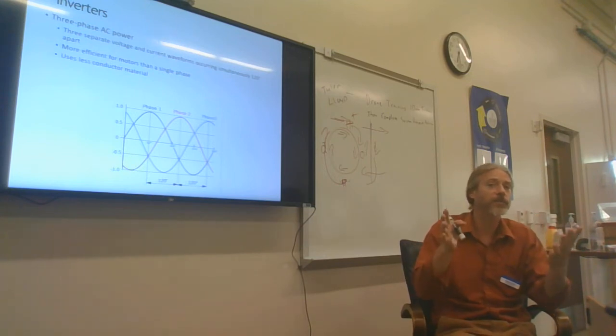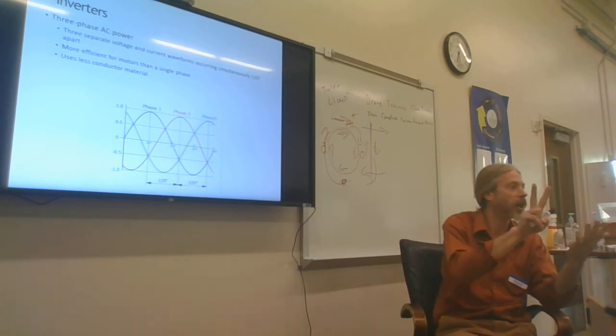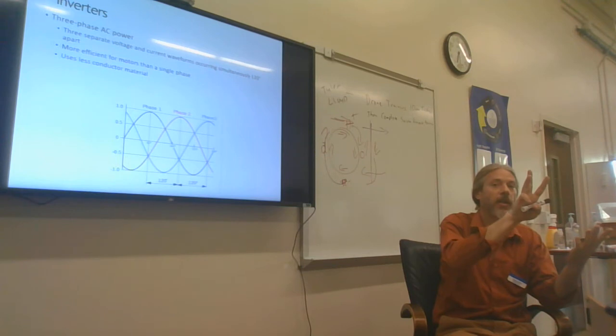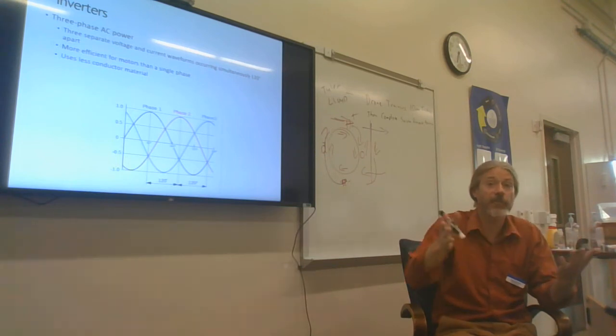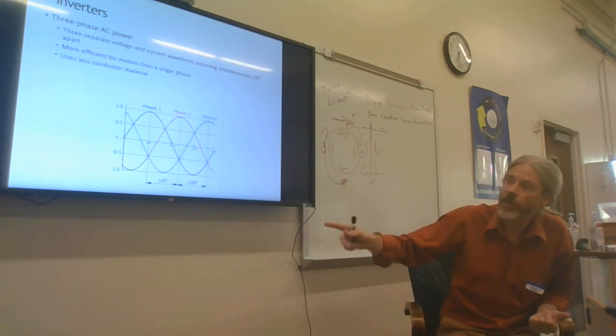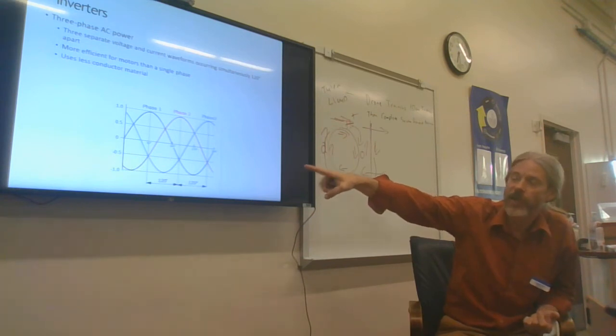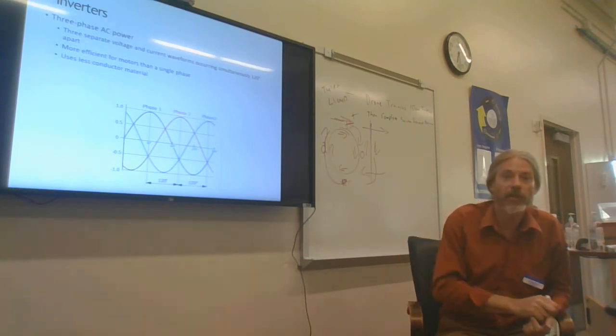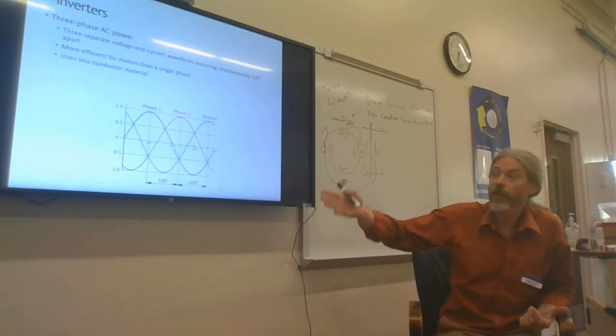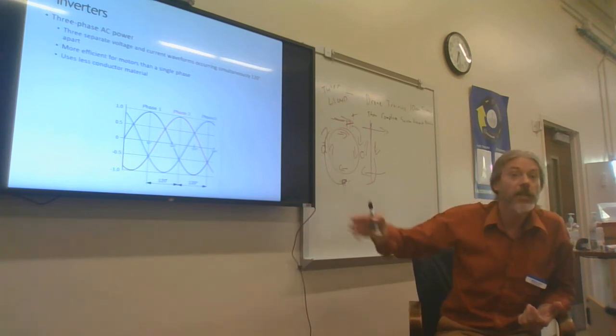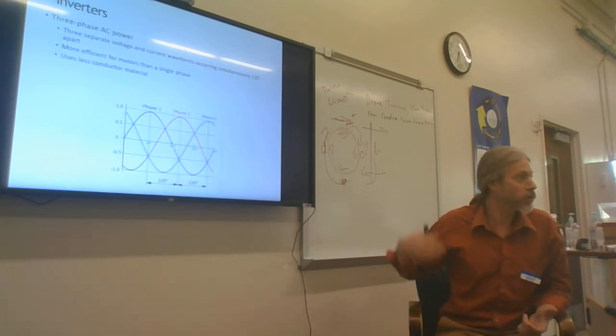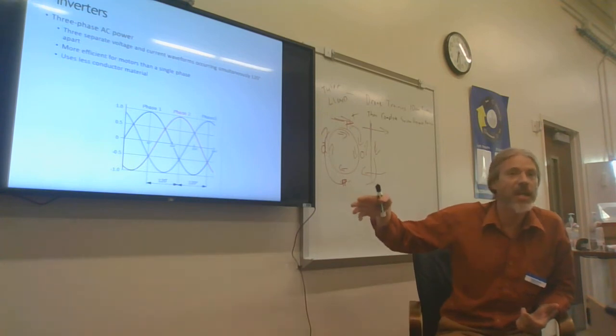Inside of that inverter, you've only got 2 wires that are hot, 1 that is a neutral, and 1 that is a ground. So inside inverter 1, I run wires from phase 1 and phase 2, and the neutral and the ground. In inverter 2, I wire phase 2 and 3, the neutral and the ground. And in inverter 3, I wire phase 1 and 3.